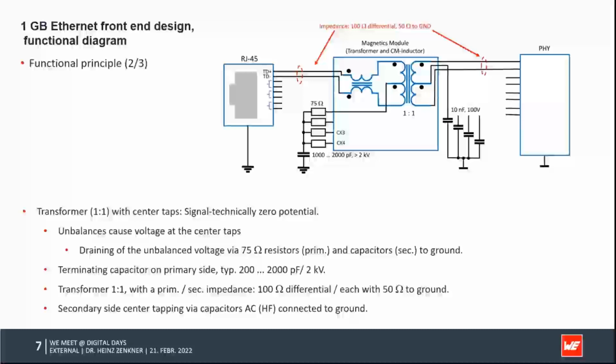And one issue, if you look closer into it, is that the reason why we have the capacitors is that we have DC blocking on the secondary side, meaning towards the Pi, and also towards the cable, which, as you can see here, blocks the DC voltages, but the AC voltages can then be drained to the center, to the ground, because of the capacitance here.